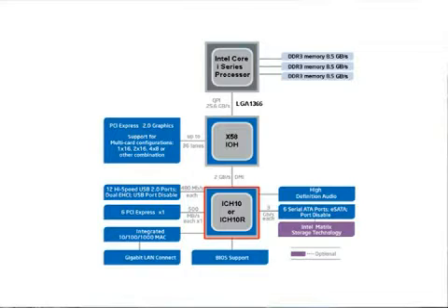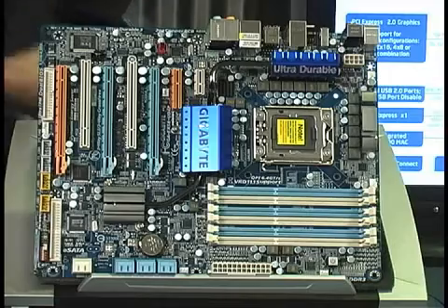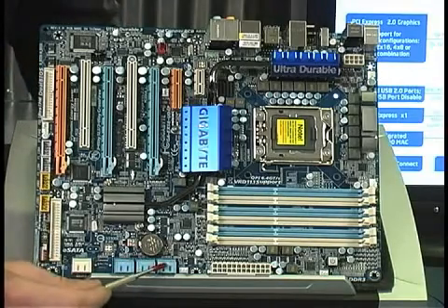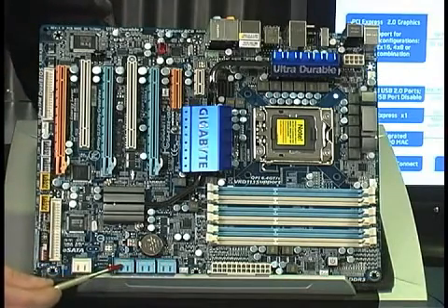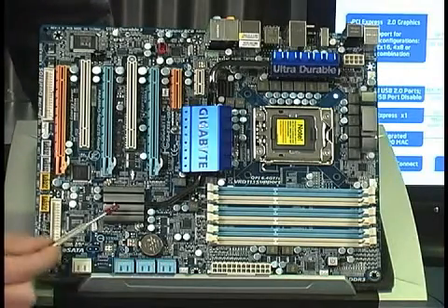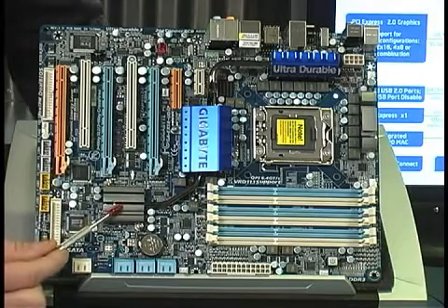Well, a big portion of this is the interface to hard drives, and what we have is 6 serial ATA ports made possible by this particular Southbridge. This one happens to be called the Intel ICH-10R. That's I/O Controller Hub 10, R for RAID Edition. And we find those ports right here. There are 2, 4, 6 serial ATA ports that are connected to this South Bridge.